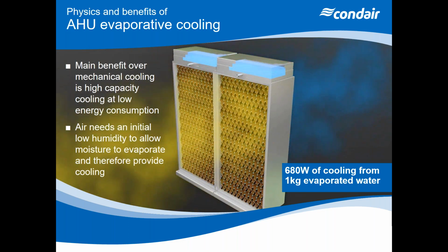And whenever you change the state of a liquid, that requires energy. And of course, the only energy source available to us here is heat energy. So as the water changes its state from its liquid phase into its gaseous phase, heat energy is taken out of the air and transferred into the liquid. So the net effect is that we reduce the air temperature.